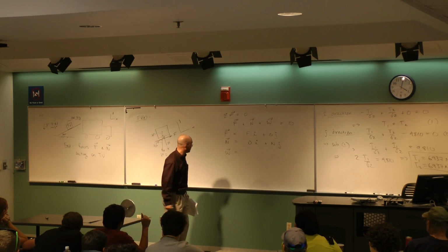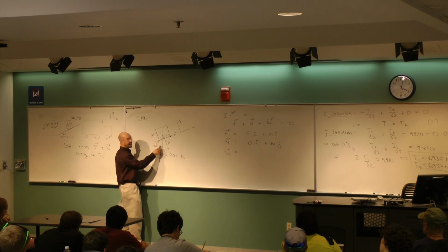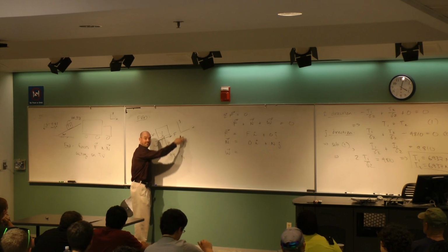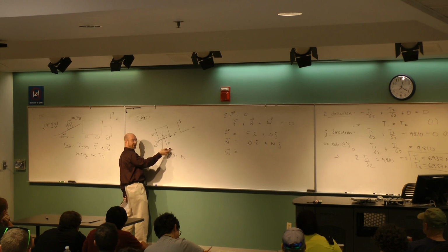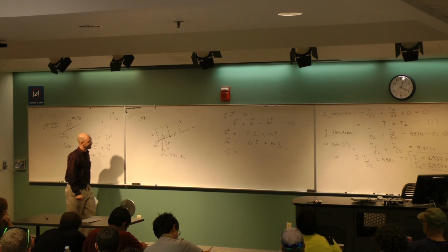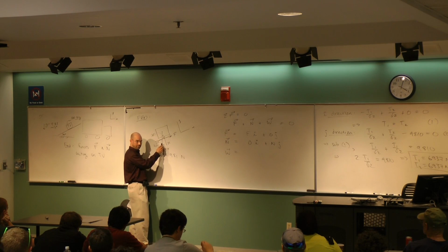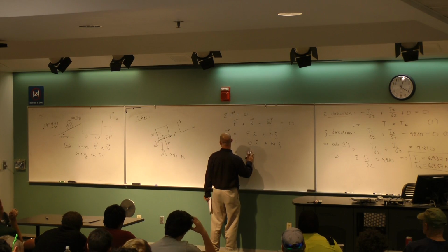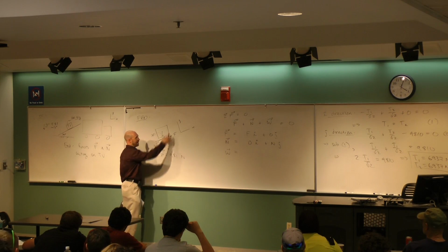The x component would be 0i. So here's W, going in the y direction, based on this coordinate system. But I'm over here, so you have to keep in mind, tilt your head sideways. The y direction's here. The x direction's here. So 981 is the hypotenuse. That's the value of the W. The opposite side is a sine. So for the x component, is it plus or minus? Down and left, opposite to these two.